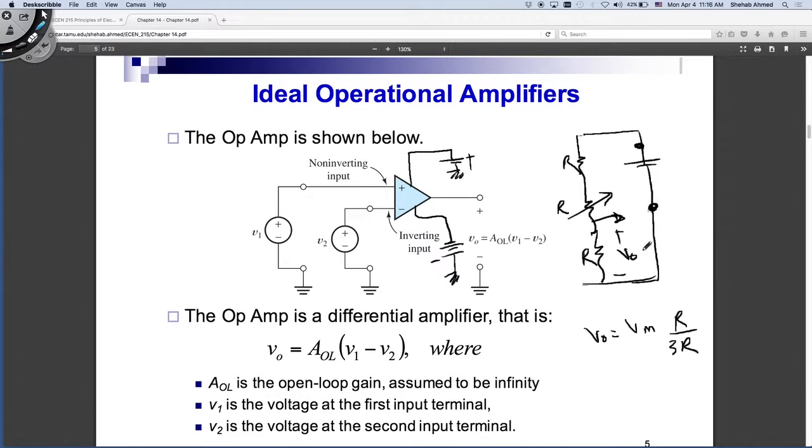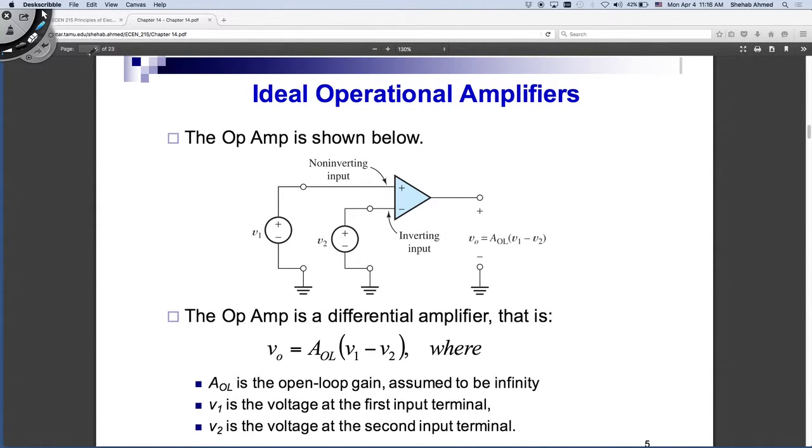But if I change this circuit to a positive value here, a resistor here, a variable resistor here, a resistor here, and a negative here, and I can make this negative greater than this positive. If I make this negative value greater than this positive value, think of this as 0 and only negative. So the output voltage here will be a portion of the negative input.